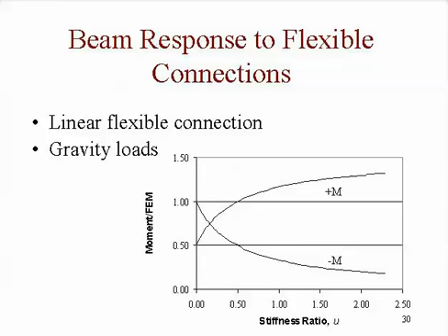And as U increases, the center line moment goes up. Now, at a U of infinity, the end moment is going to be 0, and the center line moment is going to be WL squared over 8, right? And that's simply 1.5 times the fixed end moment.